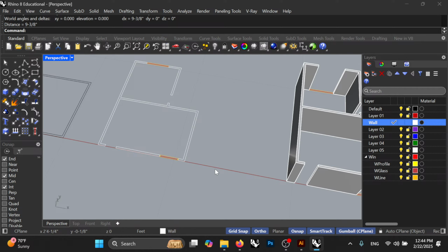If you would like to rescale the drawing that you have from centimeter to feet, let's say you're working in Mexico, everything is metric, and you would like to draw and then use those drawings in the States, then you have to use the second option. If you're working on a unitless drawing and you would like to make a unit based drawing, then you need to choose the first option. Make sense? All right. Okay.